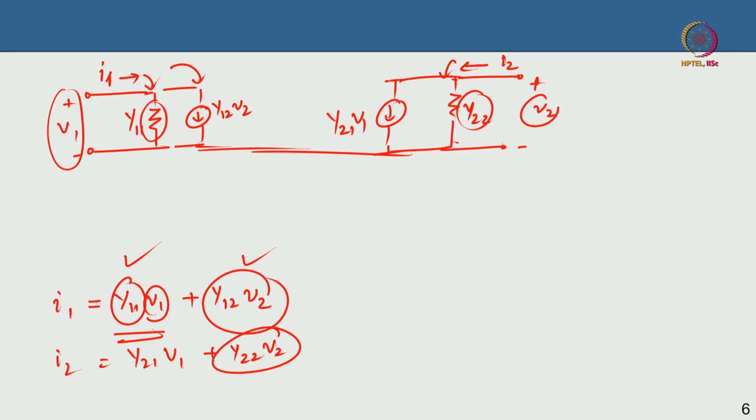So you are building a small signal model based on this Y matrix that we discussed, right. You can quickly see that this actually is your drain current, and this drain current is basically a representative of your GM. So Y21 is actually GM, the transconductance, which is basically how much gain you are getting.